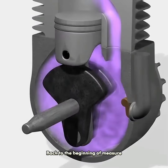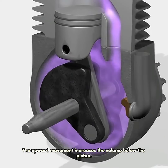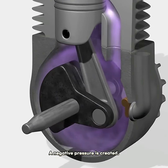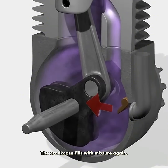Back to the beginning of the cycle. The piston is now at the bottom. The upward movement increases the volume below the piston. A negative pressure is created. This negative pressure opens the inlet valve. The crankcase fills with mixture again.